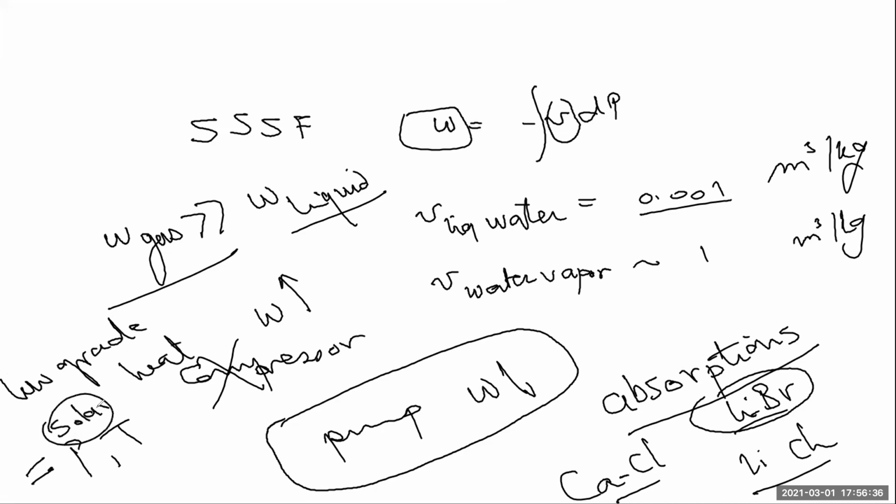You can get solar collectors to heat the diluted solution, and then vapor is going to form. The vapor will leave the regenerator, and the strong solution is going to go back again to the absorber, and the cycle repeats itself. So we are going to get this and combine it with a refrigeration system, and then we are getting all benefits out of this.